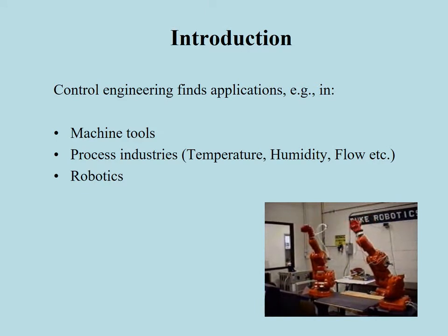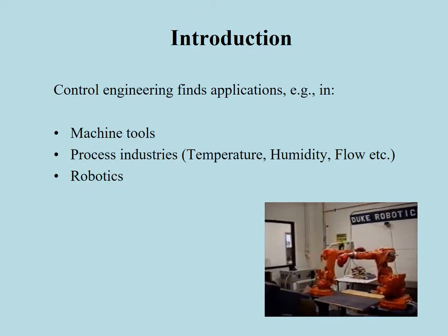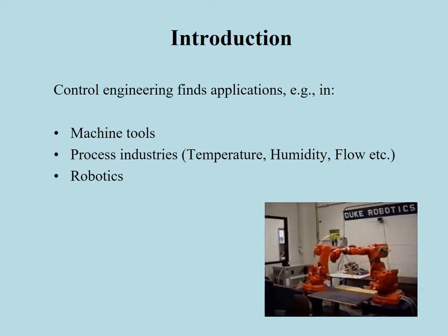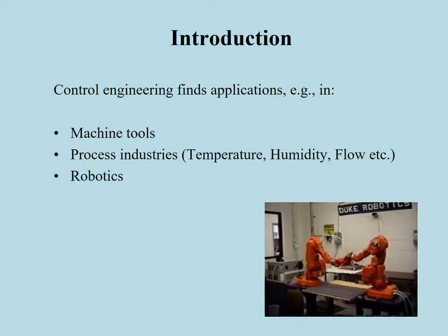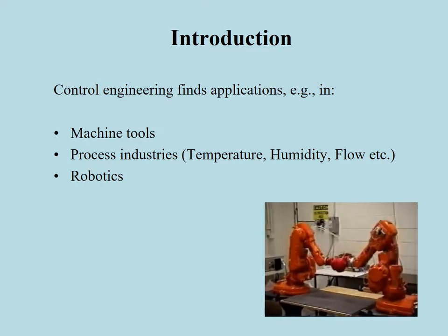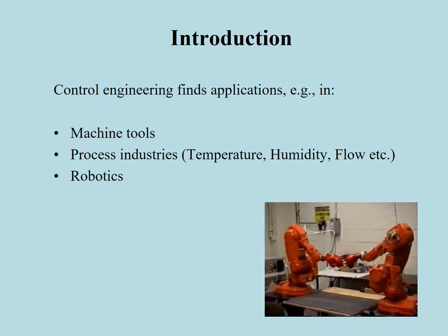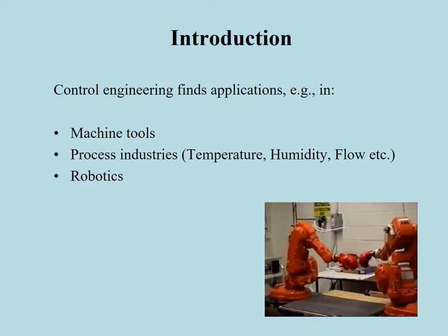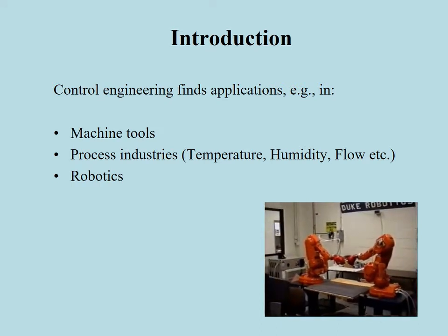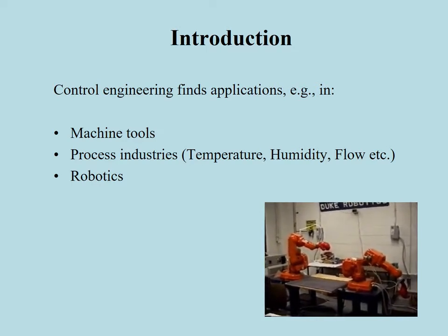In this video clip, we have 2 robot manipulators imitating a boxing match. Each robot has a 2-link arm and the links can rotate in different directions. Also, the end effector, namely the boxing glove, can move up and down and around its own axis. So you have many degrees of freedom in moving the boxing gloves. The basic problem here is to determine the motor currents driving the links so that the links are placed at correct angles so as to implement the boxing scenario.